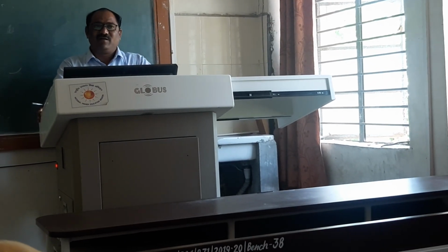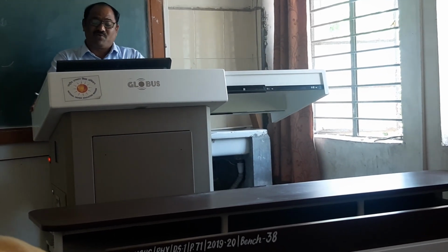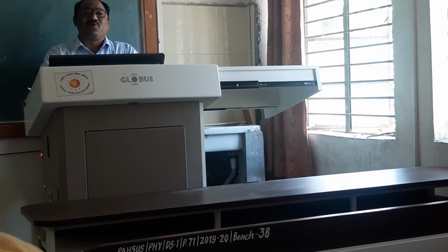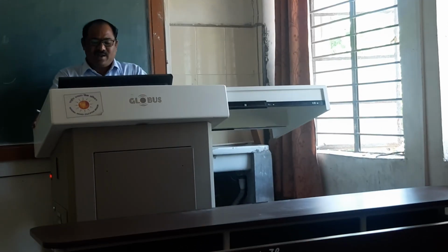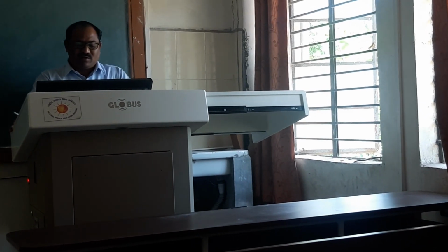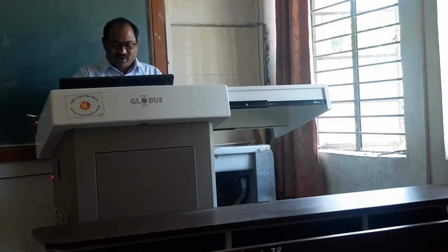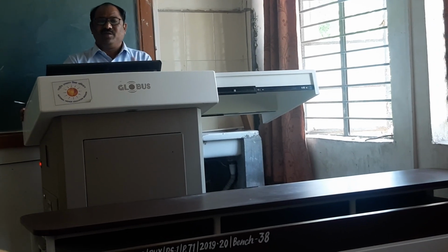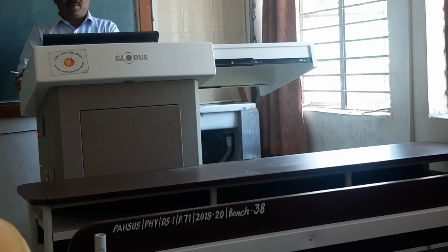Then if M0 equals 0, M1 equals 0, and M2 equals 1, mode 4 is selected. And if M0 equals 1, M1 equals 0, and M2 equals 1, mode 5 is selected. So this is the programming operation of the 8253 and 8254. You have to explain what actually happens.